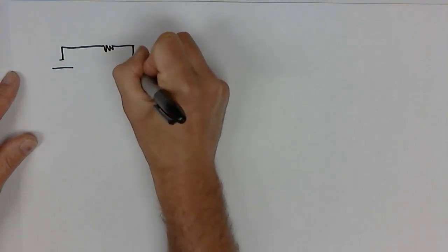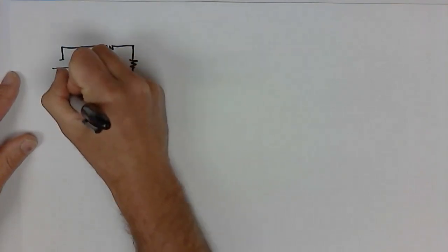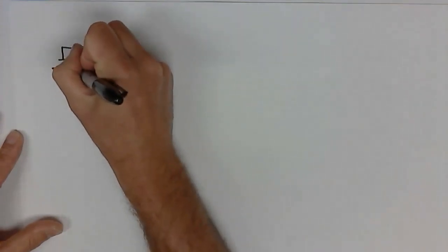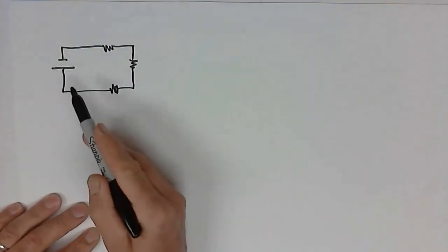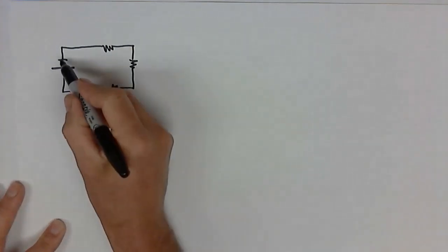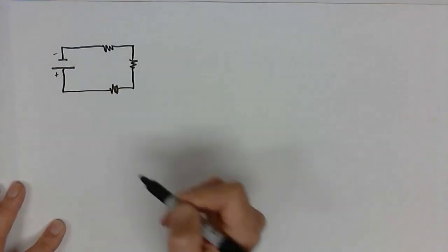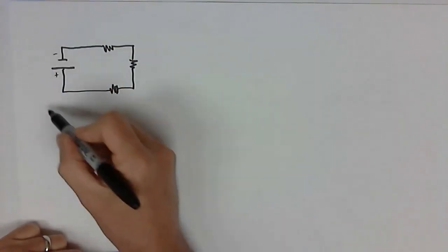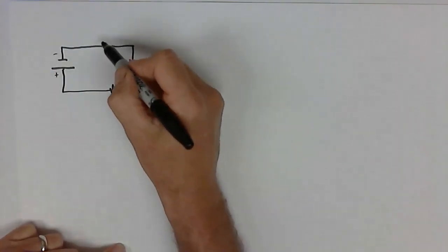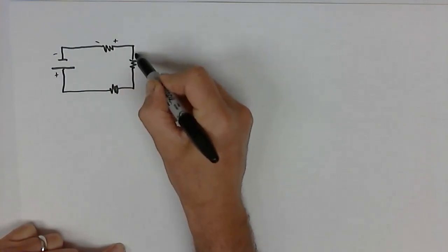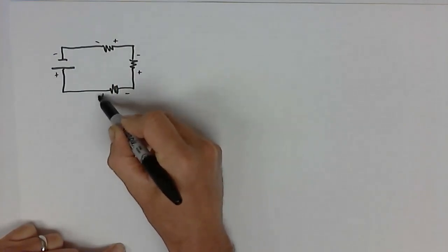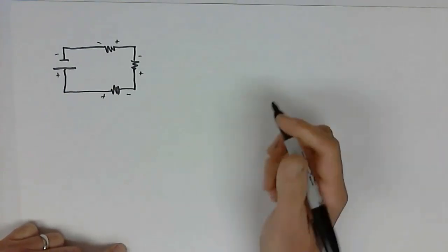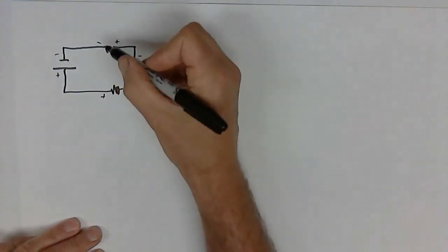1, 2, 3 chunks of resistance. There's my DC source. And everyone knows that with a DC source, the short line indicates a negative, the long line indicates positive, and that means that throughout the entire circuit, we should be able to assign a polarity to every one of our individual loads. It's important that you are able to do that. All right, R1,